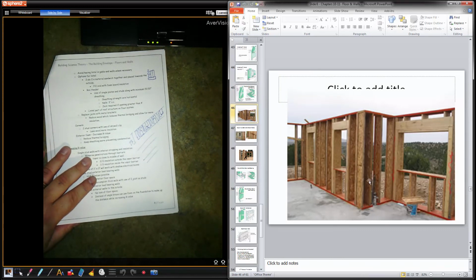Just showing thicker walls, not really anything to do with a double wall. I'm not sure why that's folded in there, but they're using floor joists here for studs. So trying to get a greater R value. The plates are rimboard. You got lintels in place. You're just getting a bigger cavity.